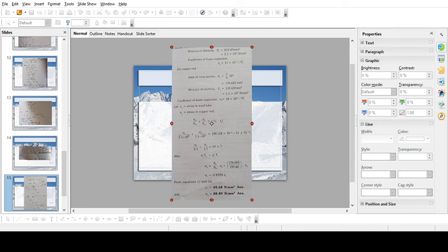Now if I calculate this, I get the stress in the steel bar, sigma s, equal to 0.8928 into sigma c, that is the stress in the copper rod. So we have two equations: sigma s equal to 0.8928 sigma c, and sigma s by 2.1 plus sigma c by 1.1 is equal to 19 into 7.